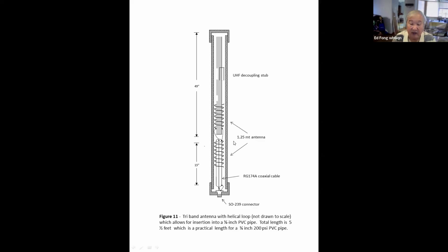Okay, I'm going to repeat this. I see the internet is unstable again. Tune the antenna with the length of coax and the type. Try to match it up. Then you'll see it match. That's really important. That's one thing we found.